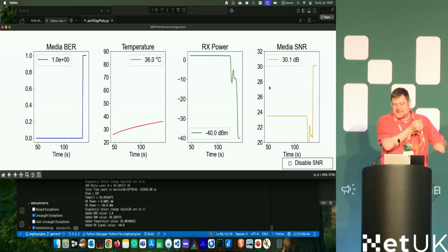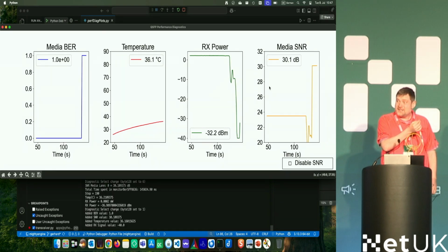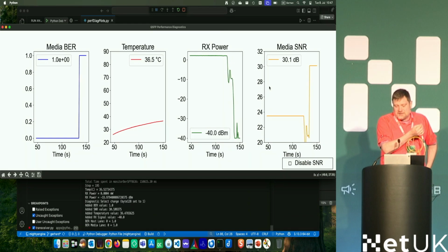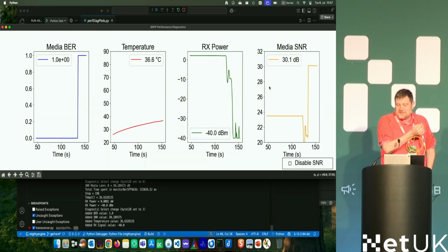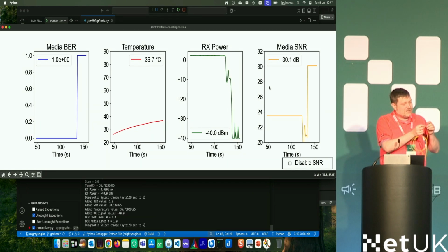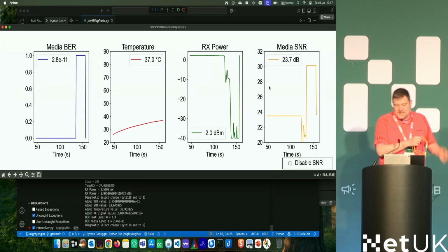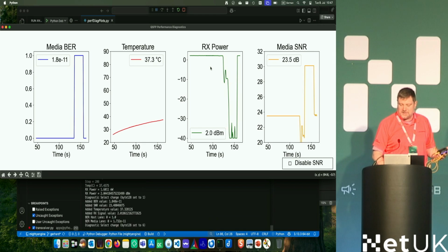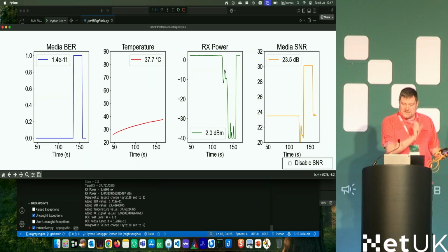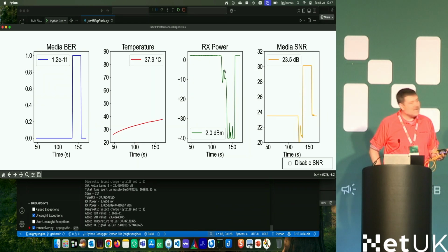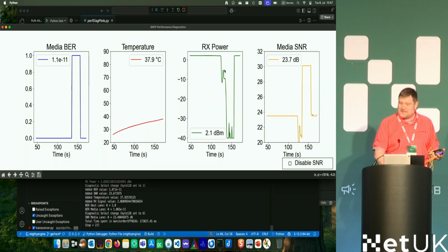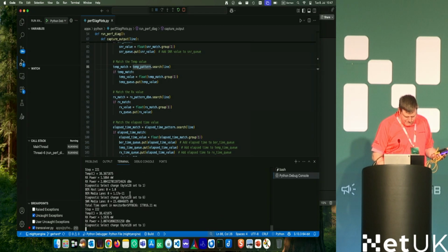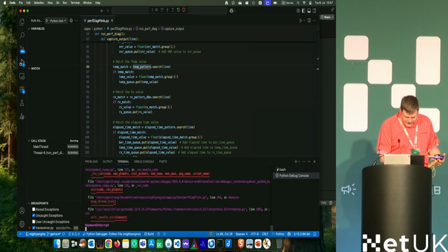And it's quite interesting how the OSNR also goes to 30. It would look like a good value, but as I mentioned previously, it's a flag that the hardware manufacturer is setting. It doesn't mean it is good, it means there's no signal. So yeah, a little bit weird sometimes, but it is what it is. So let's unbend the cable, and as you can see, you have a pretty healthy, normal Rx power, and you can see over the time axis how much and how many times and how strong I bent the cable. Right, yeah. Let's get back. I can close this.